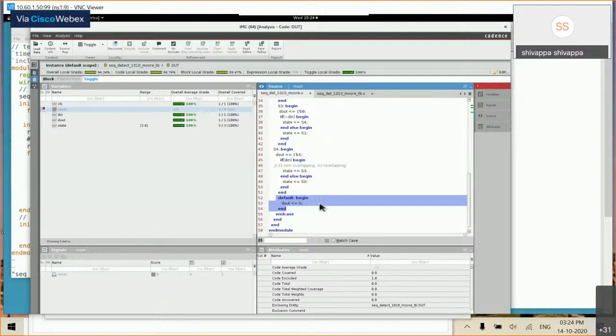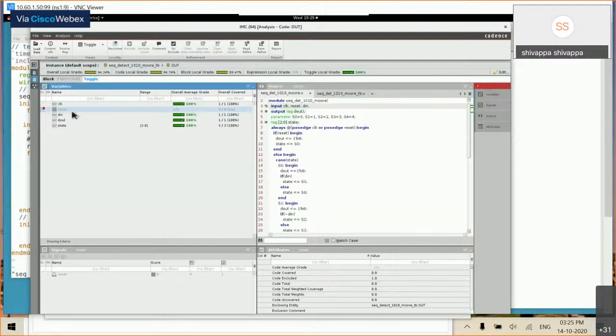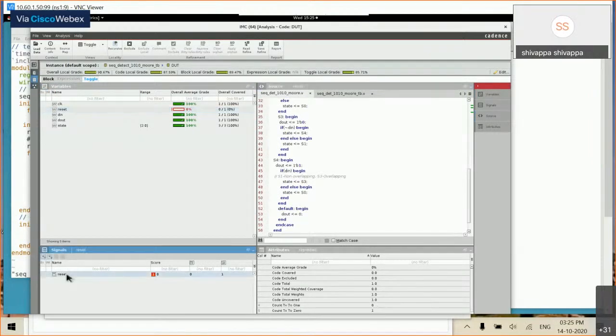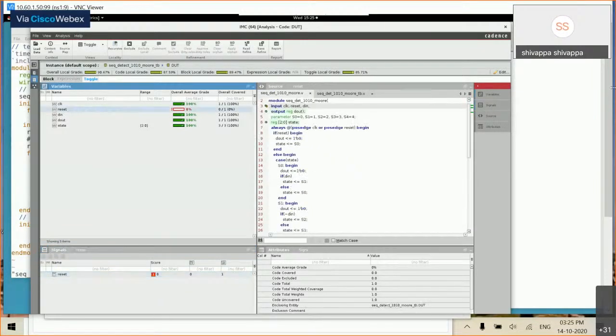So I'm showing the legal way of doing things in consultation with the designer. So the way to exclude, I showed here itself in the case. Otherwise, these should not be excluded. I agree with you. These are all not to be excluded. That's where the very first option I said, in my simulation I go and toggle my reset, and that will fix this problem, toggling of reset.